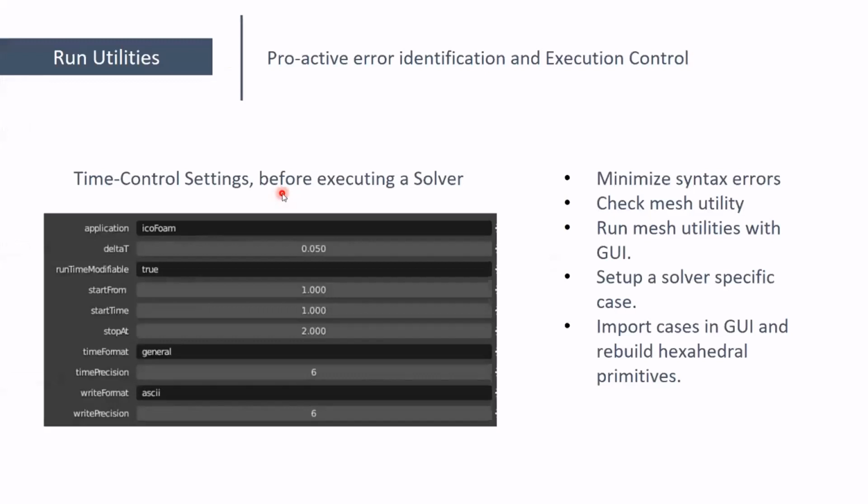Lastly, we have our run utilities, which allows time control settings for a solver. We also have ways in which we can minimize the syntax errors because the data that you're putting here is largely pre-filled. So simple mistakes in writing text is kind of avoided. We also have features wherein we can run the OpenFOAM commands from within the GUI.